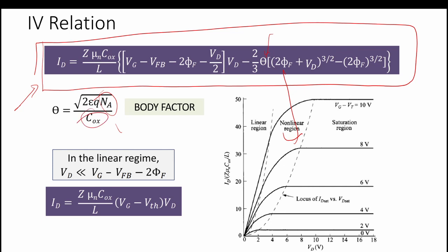So from here we can say, if we have a very high k dielectric, C is equal to epsilon by d, where d is the thickness of the gate dielectric and epsilon is the dielectric constant. If epsilon is high, this is the desired thing for a good MOSFET.